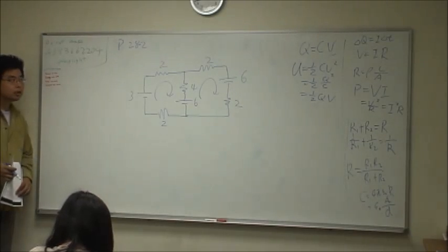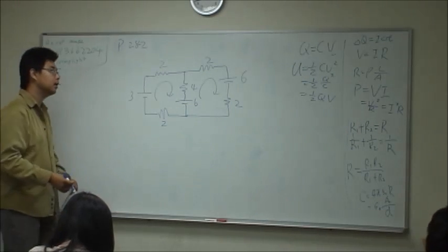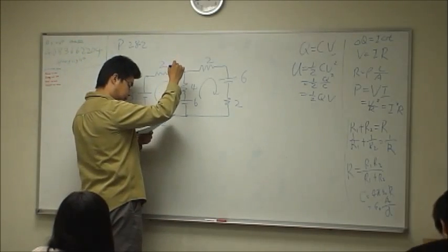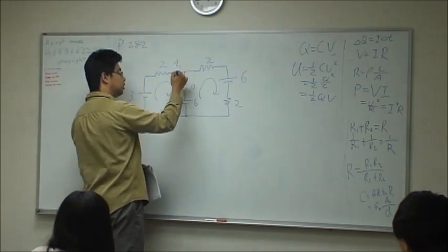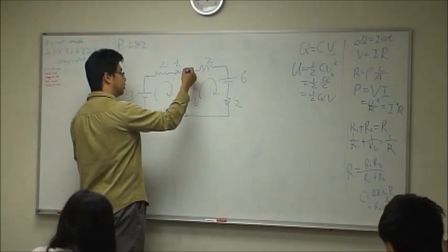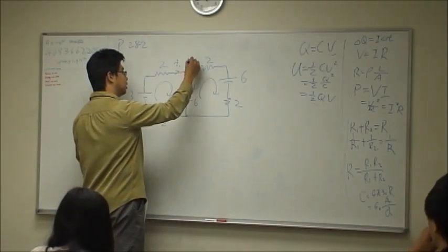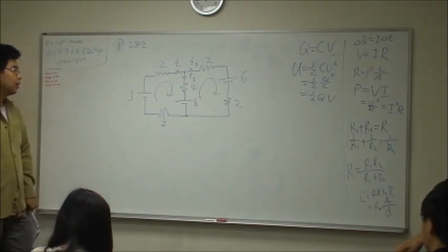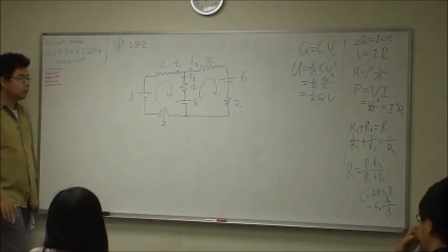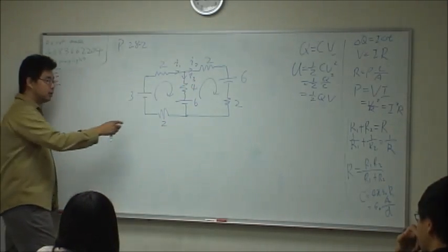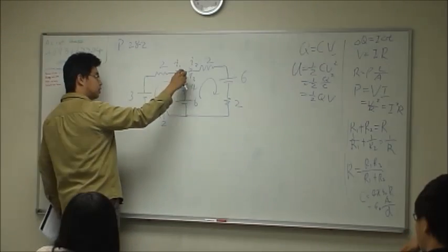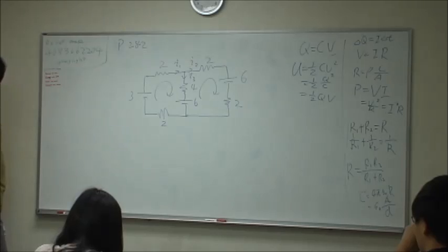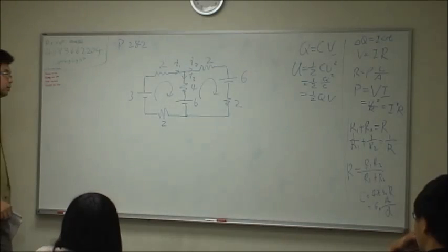Second, there are many currents, not just one of them. So there's, let's see, I1, I2, I3. I didn't follow the definition in the book, I just chose arbitrary directions. So what we found is that we have 3 definitions of current: the current goes through here, here, and here. So 3 unknowns. Let's see if we can get 3 equations.